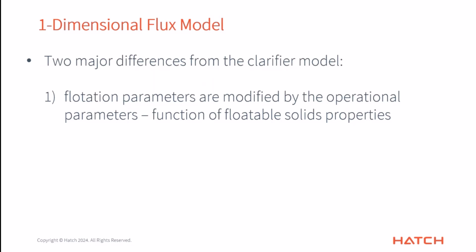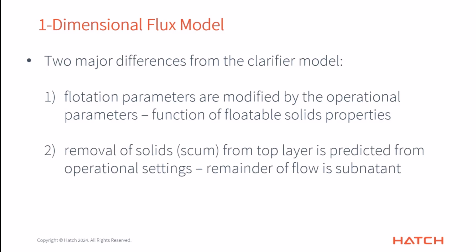the DAF unit. So what I'm trying to get at is that the density of the solids as they form the scum on the top actually plays a role in how fast they can gather up there. That's a little bit different from our settling parameters in our settler model, which we sort of treat as if they're independent.